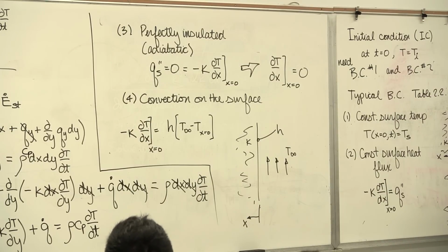The steam comes in here, it condenses into droplets at what temperature? The saturation temperature for the pressure in there, and then of course the droplets combine and they go off into the condenser hot well. Every time they condense, that temperature is the same. It's a saturation temperature. That's this guy.